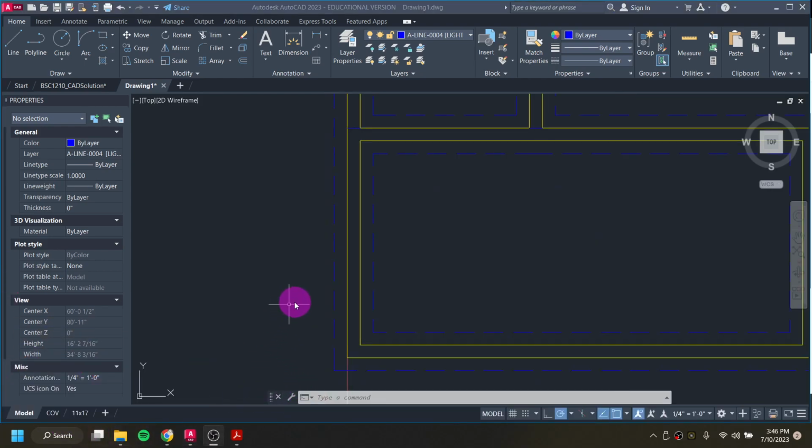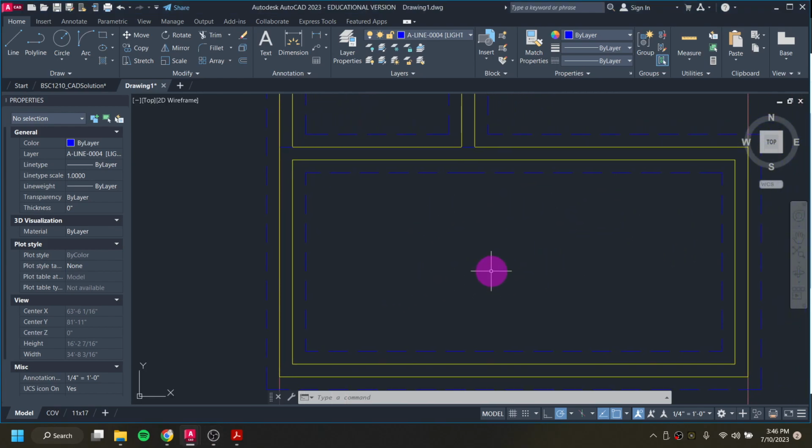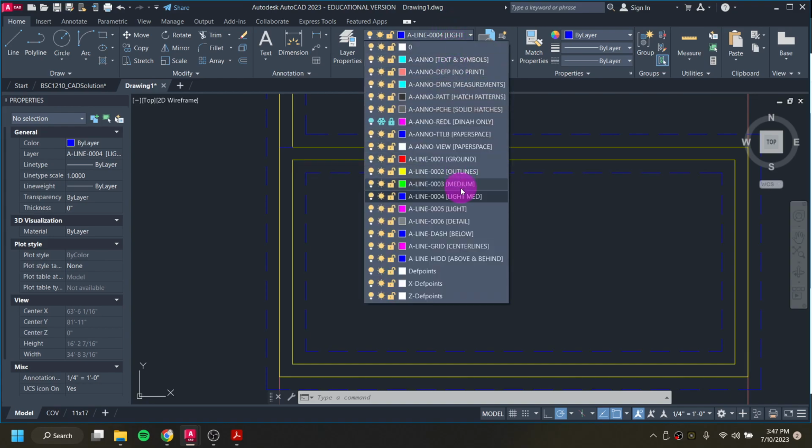So for the floor joist, what I'm going to do to start is draw one singular line here to represent one of my floor joists. And then I'm going to use the offset tool to copy it along. There are a couple of ways I could do it as well. I could use the array tool. I could use the copy tool and keep adding 16 as I do it, because you can copy based on specific amounts. But I'm going to just use offset.